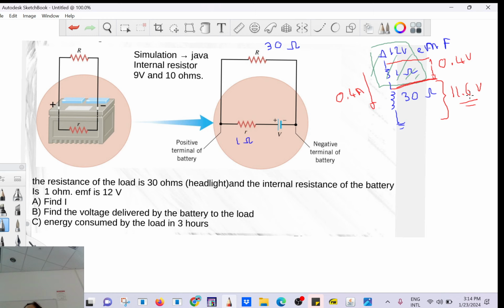You cannot see that. Like if you take a voltmeter and you measure the voltage across your car battery, you still see 12. It's only when you connect everything that you see that you don't get the 12, you get something less.